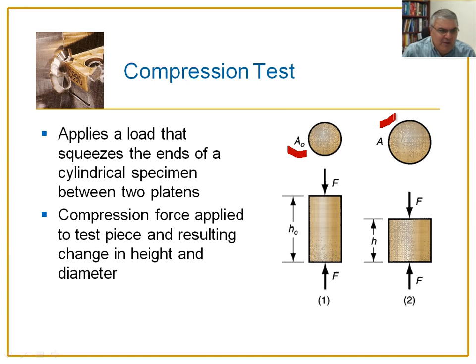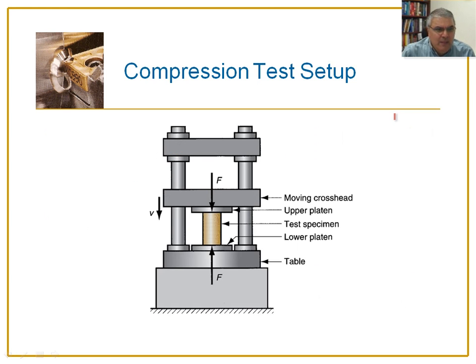What we're interested in in this test is to make sure that we're not going to have any buckling before the material reaches its full strength. So we may have a material that would perform well during the tensile test, but when we apply a compressive force to it, it may buckle before it reaches its ultimate strength. So that's very important for us to study for any material.